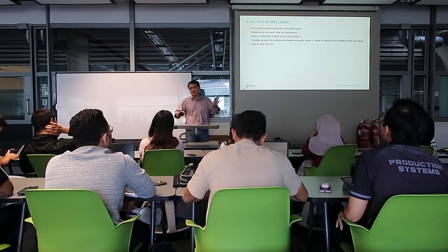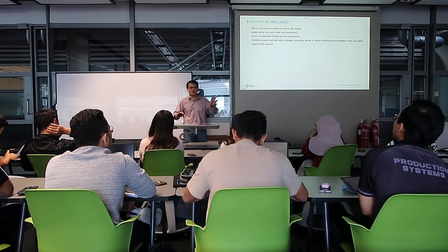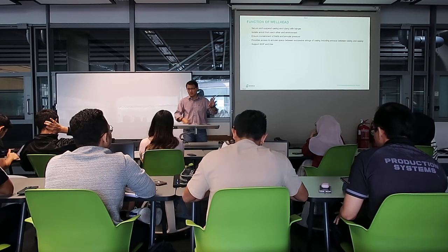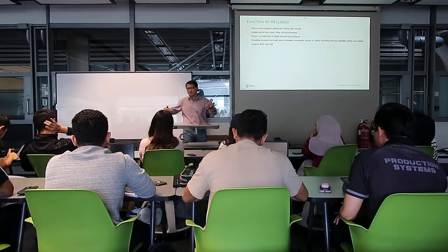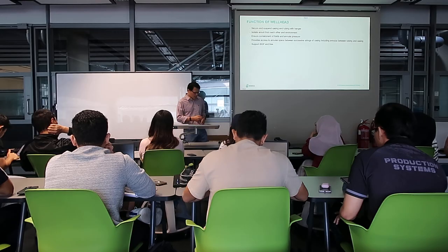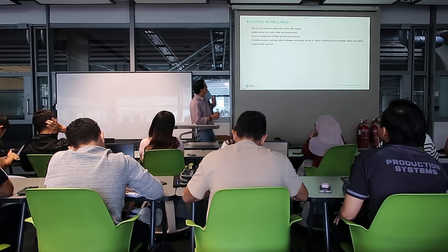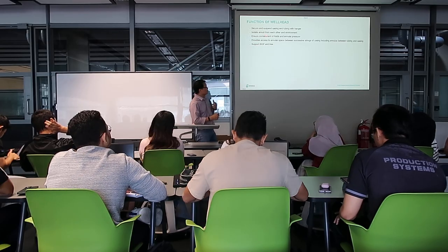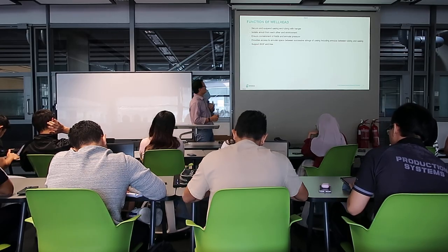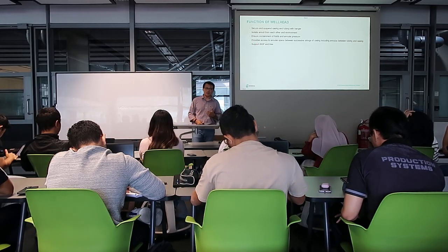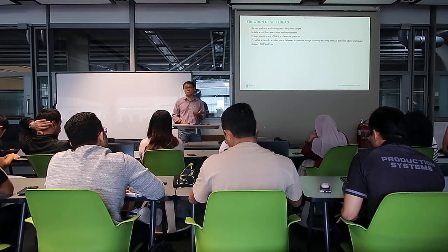When we push to deeper limits, sometimes if we start seeing a 600-700K casing string, that's considered quite deep, and we might actually have to see the casing head take that kind of load. So that's how we talk about the load, and then we seal off, then the initial pressure containment that I emphasized just now. And each annulus we should be able to access as we come to a surface wellhead.